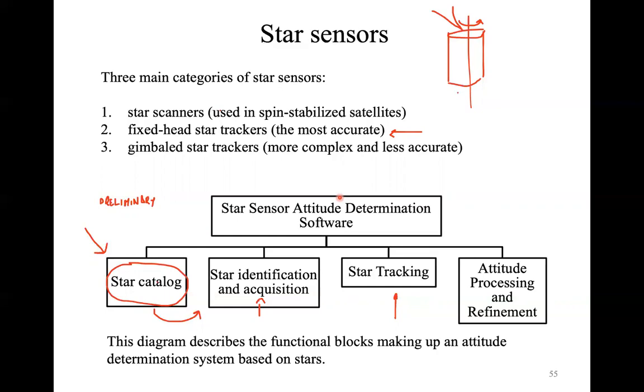And in order to recalibrate this instrument, you can use the measurements from the star trackers to recalibrate the gyroscope itself. So you can, with the extended Kalman filter, include other parameters in your solutions. That's what we're going to see on Thursday.